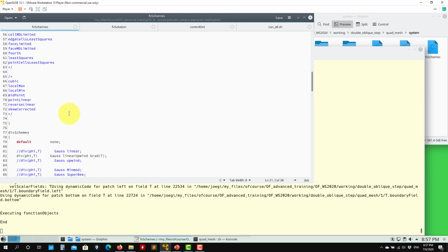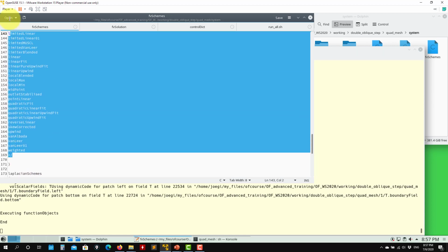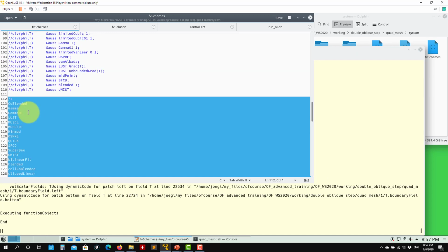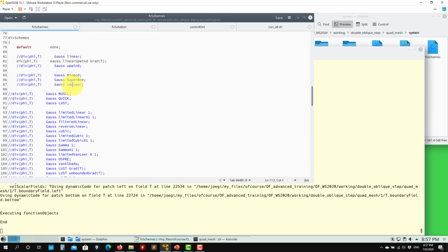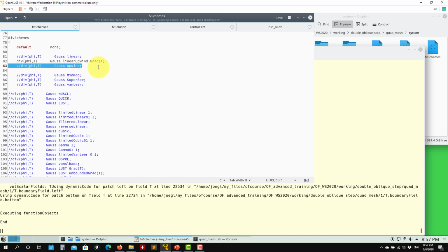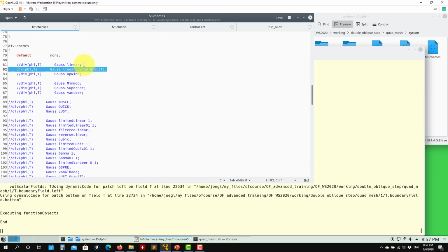Okay, this is the convective term, and we saw that you need to look at all these options. These are all the schemes that you have implemented there. If you're doing the theory, probably yes, you can look at that, but don't get lost there. You need to know that you can use Upwind to stabilize the solution. Upwind always gives you a solution, but it's very diffusive, so it will highly underpredict your values. Linear Upwind probably is the best choice with a good gradient limiter. Then we have linear that is very accurate, but it's oscillatory. And then you can choose a good TVD method.